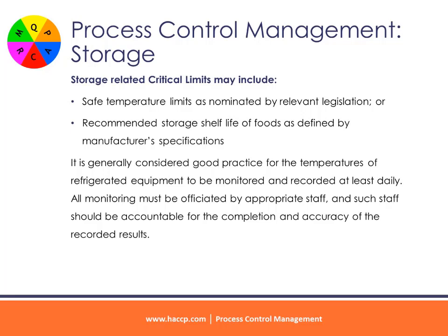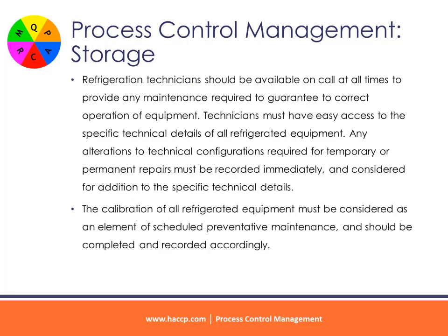It is generally considered good practice for the temperatures of refrigerated equipment to be monitored and recorded at least daily. All monitoring must be officiated by appropriate staff, and such staff should be accountable for the completion and accuracy of the recorded results. Refrigeration technicians should be available on call at all times to provide any maintenance required to guarantee the correct operation of equipment.